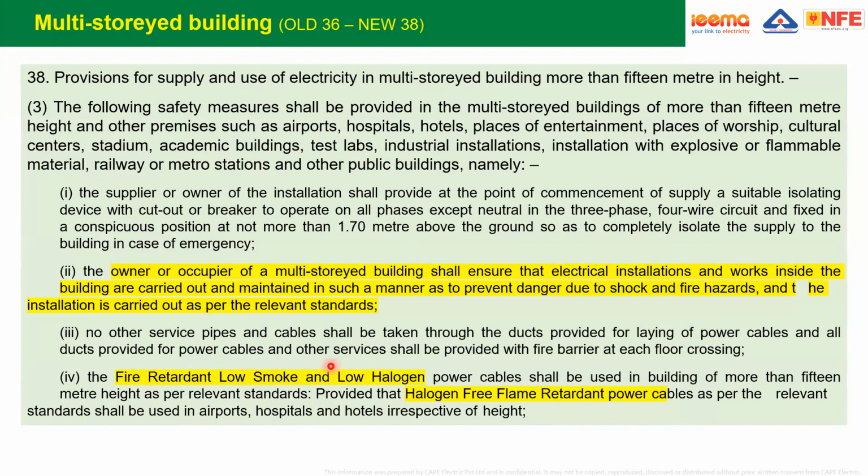Now, in the CEA regulation, are these resistances there anywhere in the regulation? I don't actually recall the part number or the clause, but the electrical inspector, whom we have been in conversation with, informed of a table which I'm not able to recall right away, and they mention all the resistance values of class 5 conductor, which is again contradictory to NEC, which talks about CR values very close to class 2.